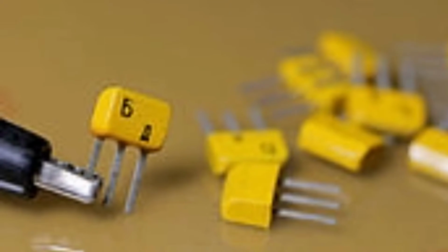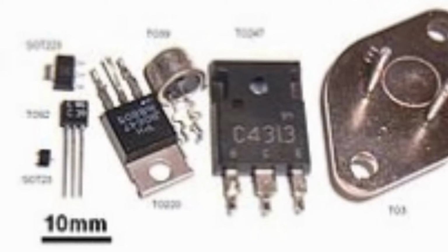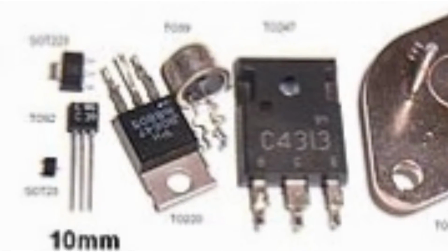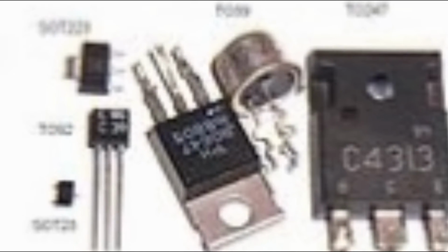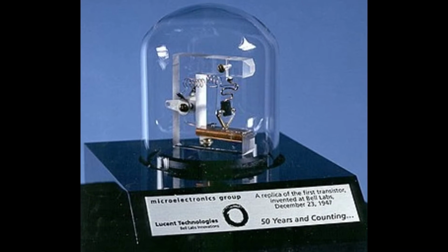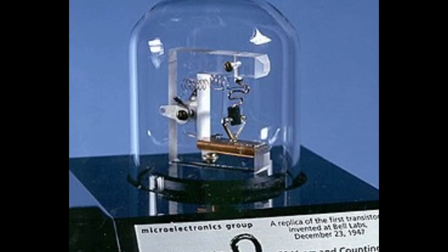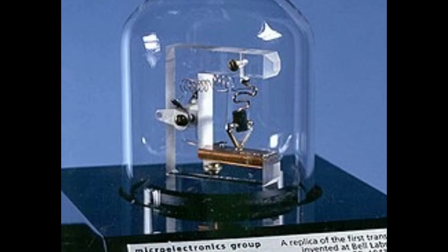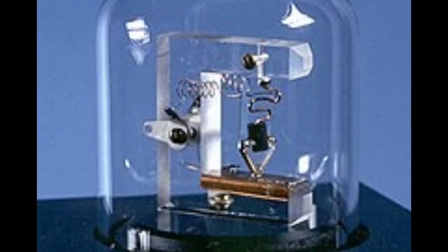The essential usefulness of a transistor comes from its ability to use a small signal applied between one pair of its terminals to control a much larger signal at another pair of terminals. This property is called gain. It can produce a stronger output signal, a voltage or current, which is proportional to a weaker input signal, that is, it can act as an amplifier.